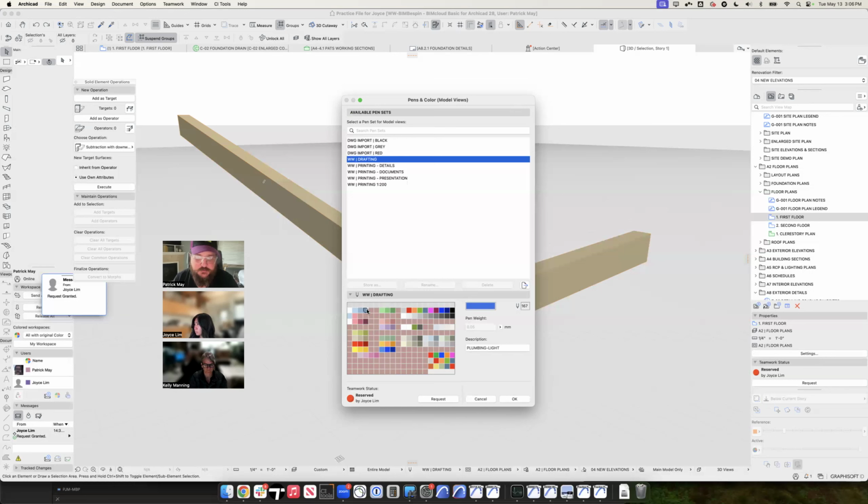I'm going to get to this group of pens last. These are our composite pens. And this sort of leads into our session we're going to jump into tomorrow morning. So I'll end on that note. This group of pens right here, these are our drafting pens. We do draft over the top of our elevations in order to give that depth of building because there is no effective way to show building outlines at varying thicknesses. So these are literally just a 0.01 to 1 millimeter pen as drafting pen weights. They're also used for details or supplementing interior elevations.